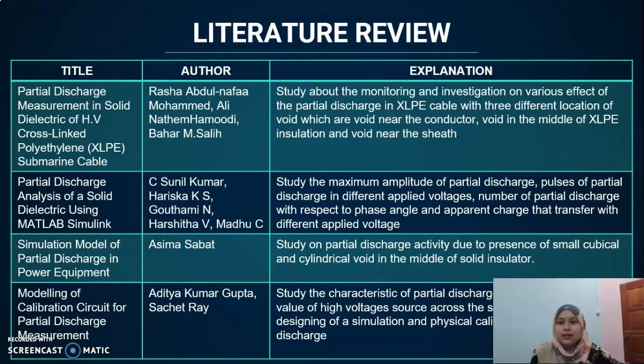Next, the title is Partial Discharge Analysis of a Solid Dielectric using MATLAB Simulink. This paper studies the maximum amplitude of partial discharge, bursts of partial discharge at different applied voltages, number of partial discharges with respect to phase angle, and apparent charge transferred with different applied voltages.